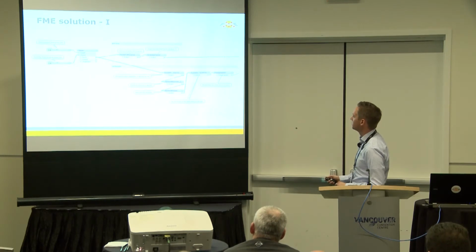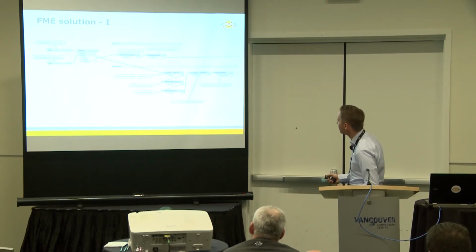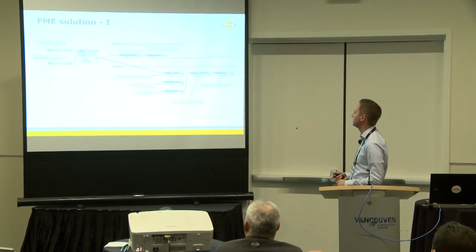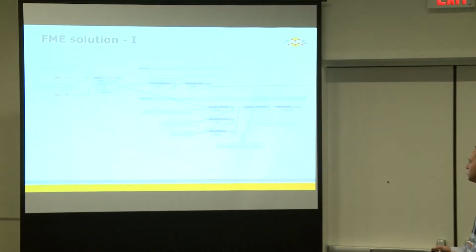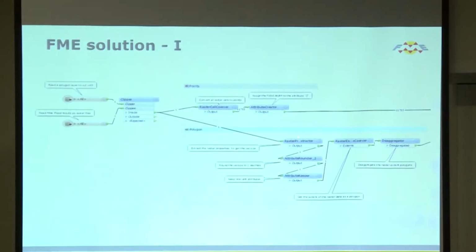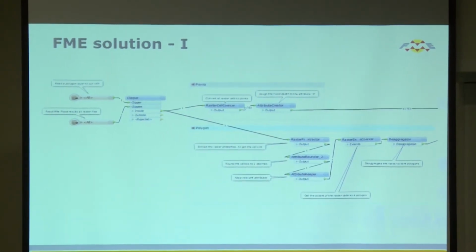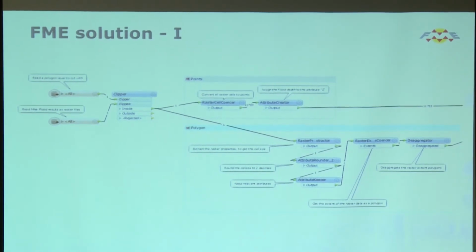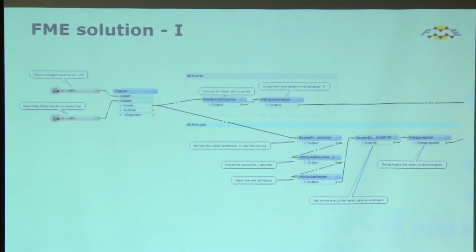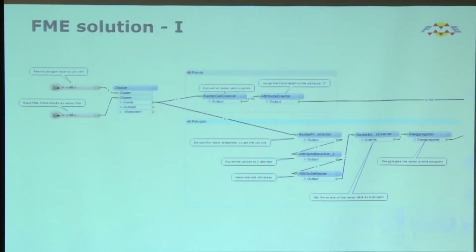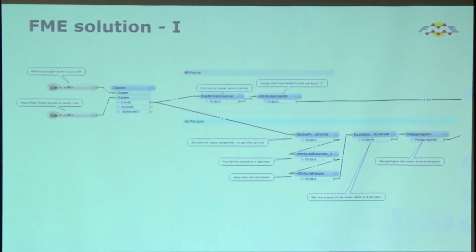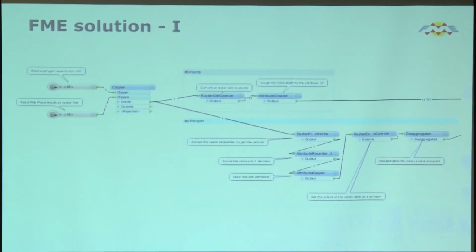So up here, I just convert it to points and just rearrange the set attributes. I extract the properties here. With the raster property extractor, I think it's called, you can get the spacing in X. So it makes it dynamic. Normally we use the same type of spacing, but sometimes we use 1.6 meter and 3.2. So this makes me independent, so I don't have to think about the size, and it takes care of it automatically.